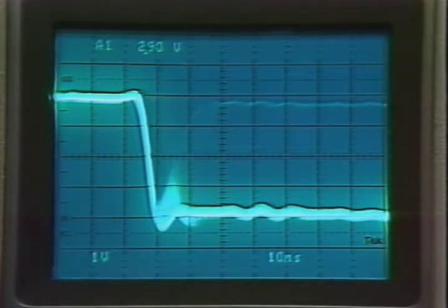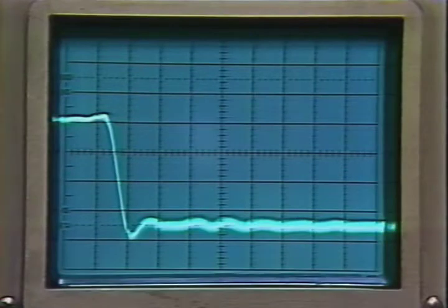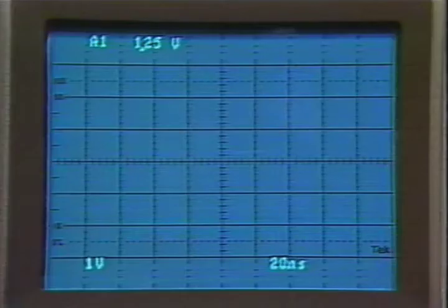This is a metastable flip-flop. Occasionally, it returns to a logic high rather than switching low. This can happen when a clock edge is close to the data edge. On a normal scope, these events are quite invisible against the bright background of normal events. They occurred too infrequently to excite the CRT phosphor.